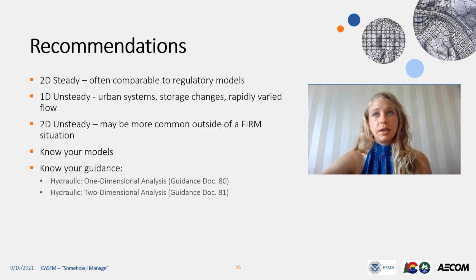Additionally, if you're handed a design that uses velocities that are much higher than expected, maybe the engineer could be using an over-conservative methodology. Finally, know your guidance. FEMA has their hydraulic guidance documents for 1D and 2D analysis, 80 and 81, that outline pretty well when certain scenarios are most applicable. And I'm sure as the hydraulic world shifts more towards 2D, these documents will be changing and updating.